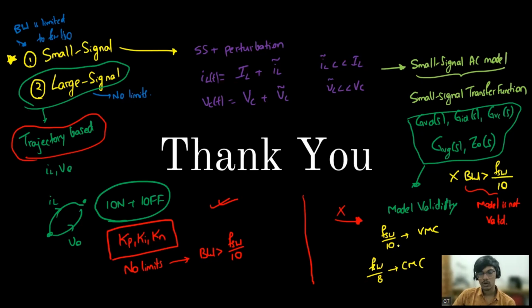But say I do not know anything about KP, KD. What values will I put? 1, 10, 2, 3? I cannot randomly put values now, because it has to be designed, and directly going to the large signal would be difficult. So just to have some basic understanding of what values I have to put, in order to get into that ballpark of the KP, KD values, we start with the small signal pole zero cancellation, which is a very rudimentary method, so that we can get that okay, KP is approximately 10, KD is approximately 0.1, KI is approximately 7.